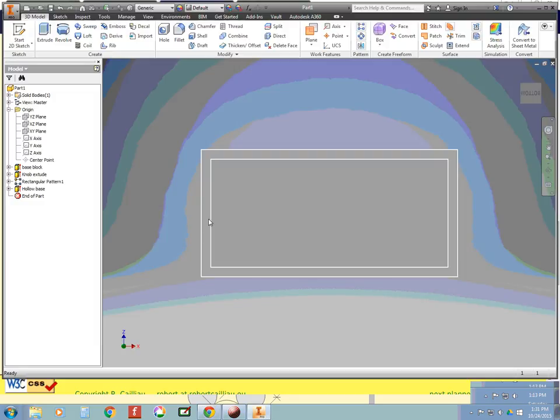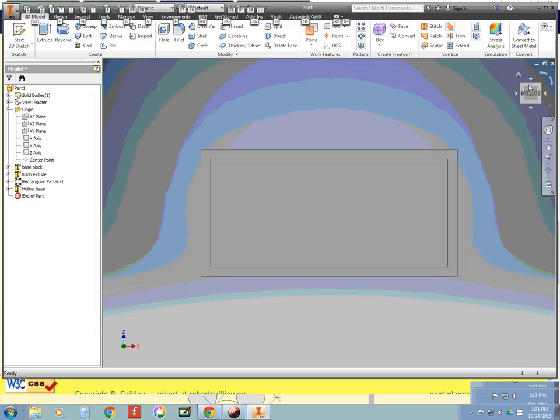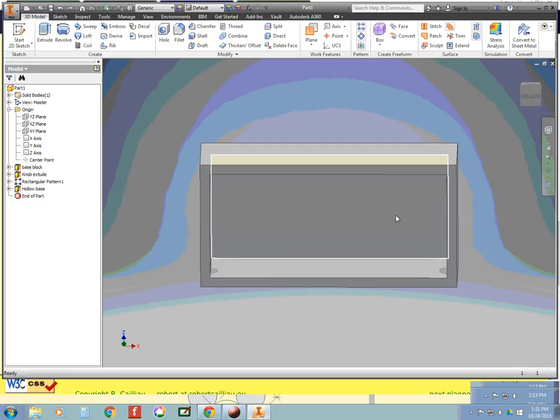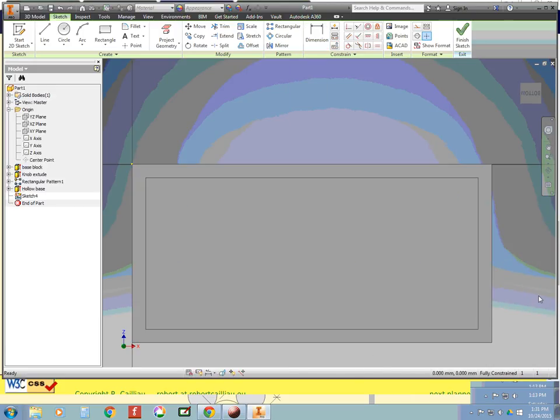That's these. And when we do that, then we want to pick, let me show you this. This surface right here is going to be the surface we draw on, and then we're going to extrude toward us. So again, if you right click and choose New Sketch, it picks the surface that you click on as the surface where your sketch is created.